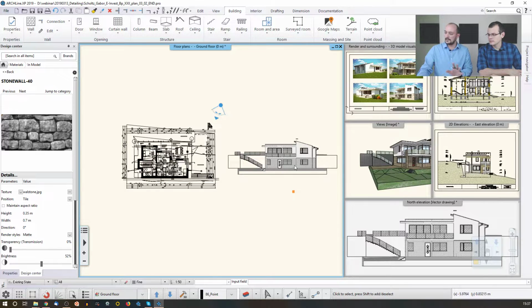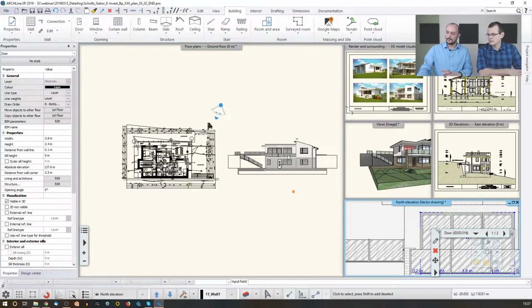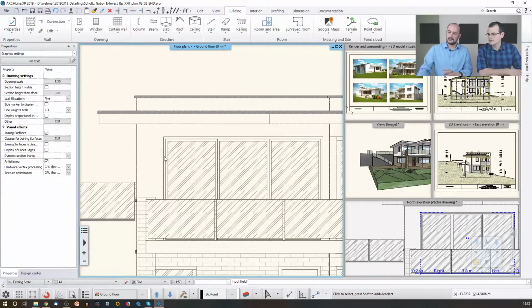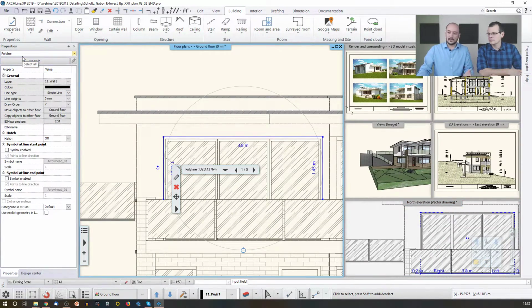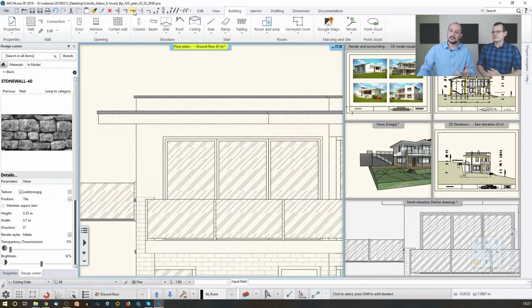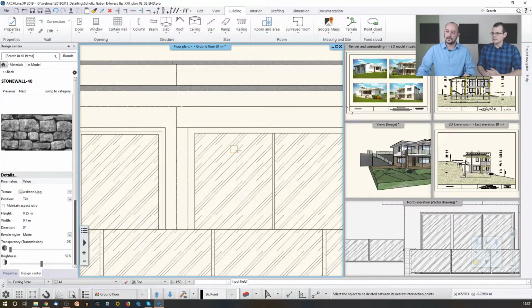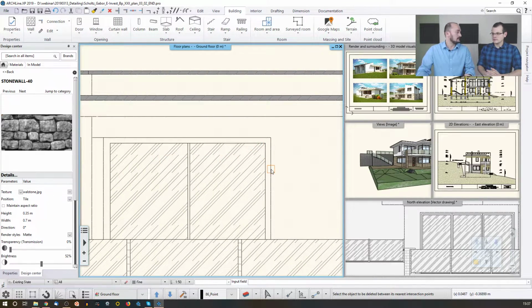The difference between this and that is that when I zoom in here and I select this, this is a door, and when I do the same thing here, this is a polyline. And with the polyline, I can do even things that I cannot do here. I cannot erase this line because that's part of the model. But I can do that here by just simply using this. This is a tool which I like a lot, and which allows me to erase parts of the drawing. So this way you can make changes that would otherwise not be possible other than modeling it.